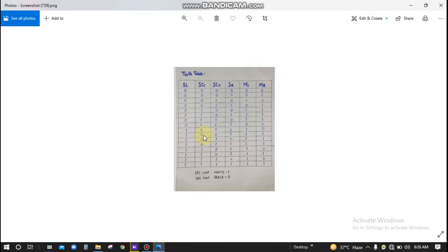It means both central sensors are on zero, and the left and right sensors are on one. The other two sensors are detecting a white surface, so it tells the motor to keep moving. The robot is moving in a straight line.